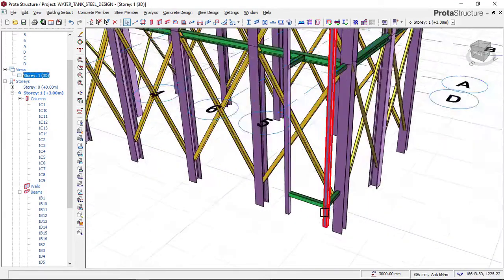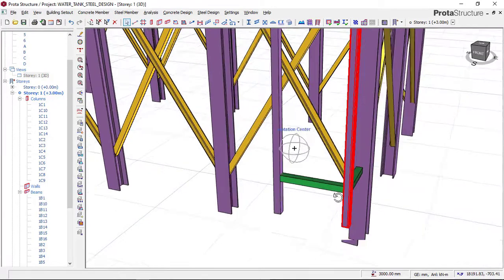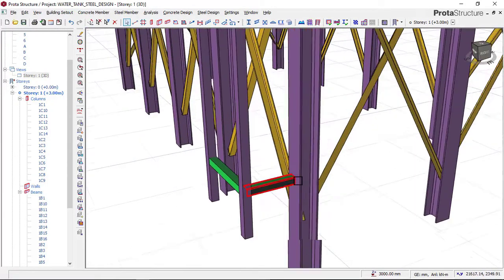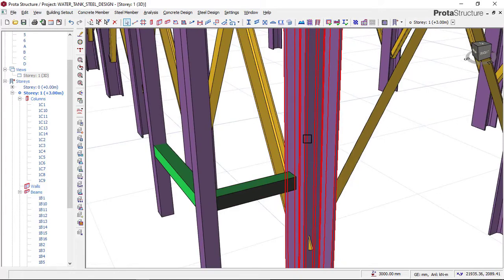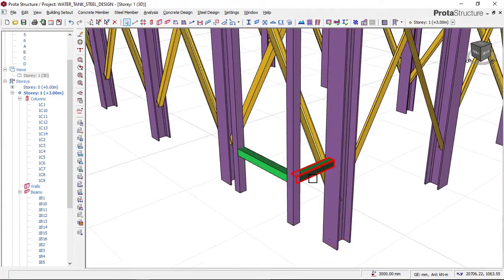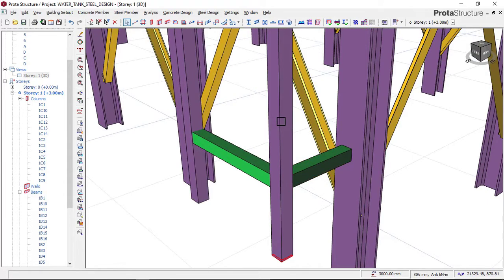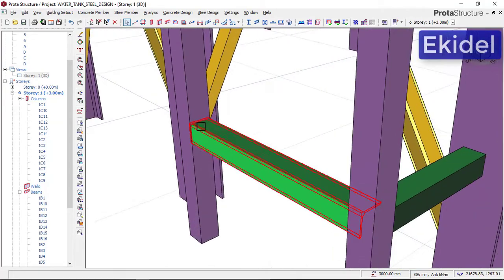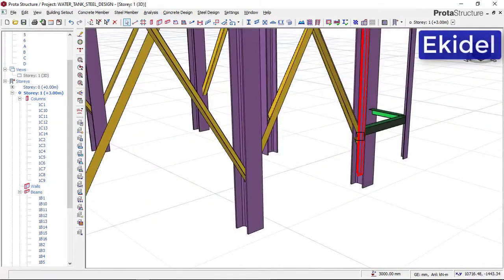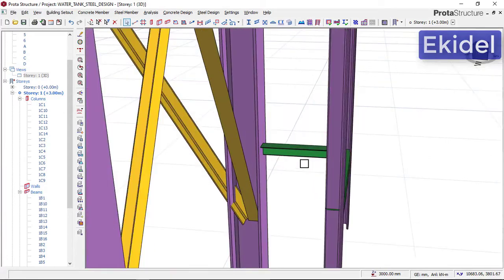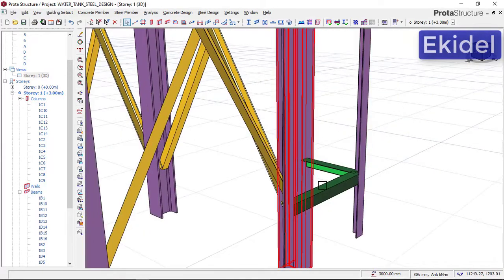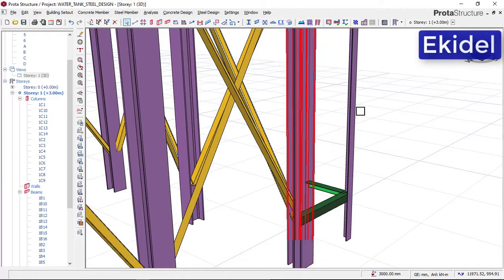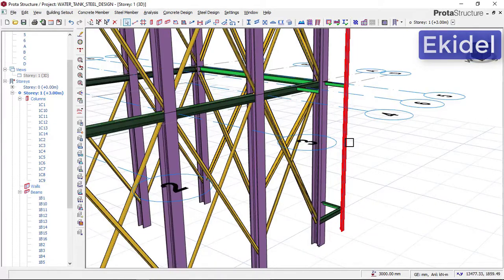Now this is the kind of connection that we are going to use. You can see that this member is being connected to this steel column here, which now supports this staircase column right here. And with this, since this is already supported, this can also anchor on this place using a welding connection, and also be welded to this place to hold down this place. Now with this, this staircase ladder connection is perfectly okay. The next thing to do is to create the ladder of the staircase, which we now start.